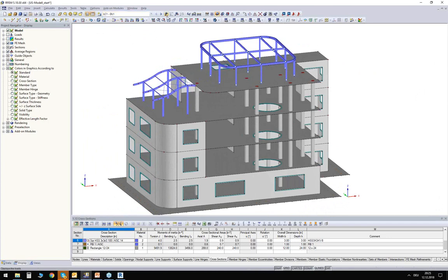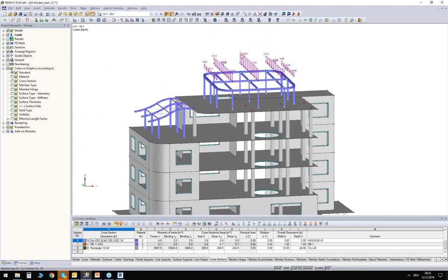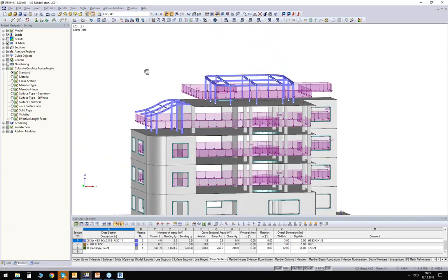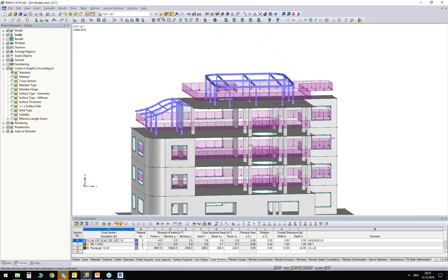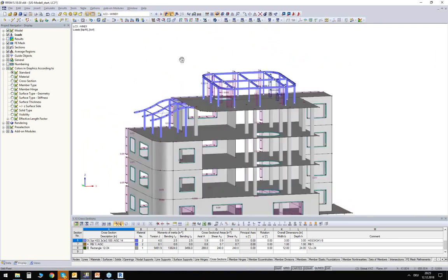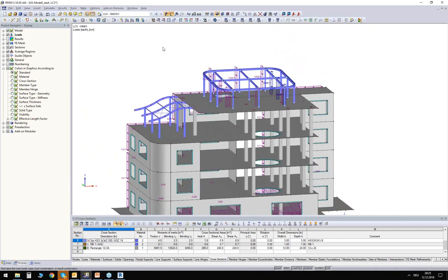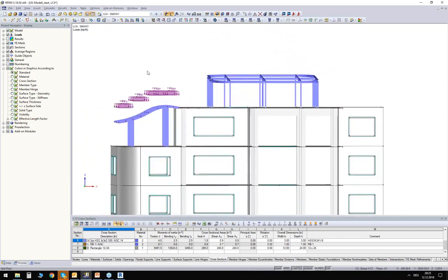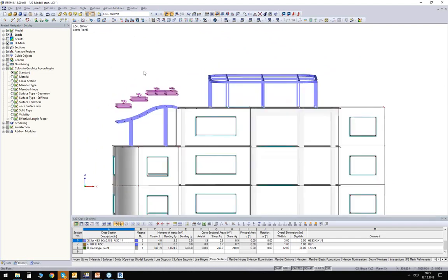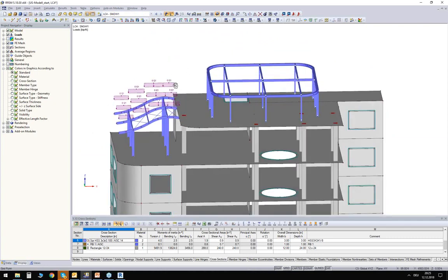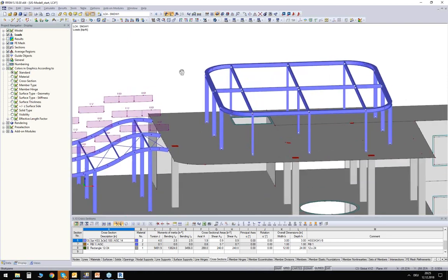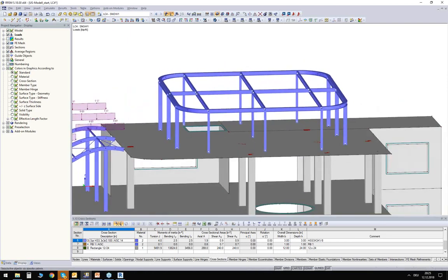And I can also take a detailed look. I have some dead loads, additional dead loads. In this load case, I have some live loads on top of the slabs. I have some wind loads and also some snow loads. I can see directly that the person who created the loads in Revit forgot the snow loads, for example, here on this steel construction. Again, this is something I can, of course, also add in RFEM.